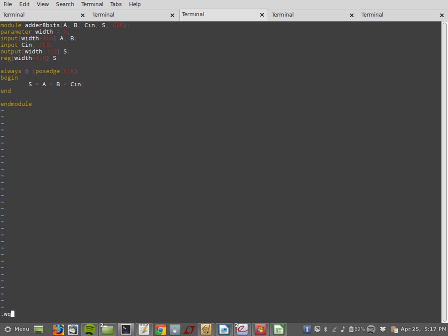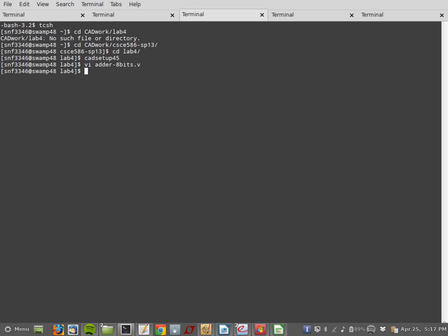So this is my Verilog file. This is not the best way to design an adder, by the way. Adders are not synchronous like this. Don't take this as a good example. We don't have a clock in an adder. I just forced it to be synchronous because usually when you synthesize something, it needs to have a clock. Okay? Now, we go into our synthesis stage.